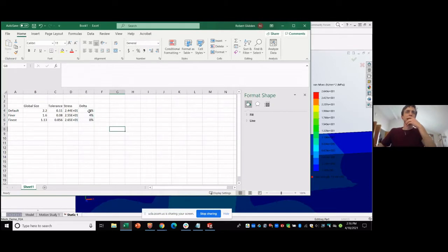To a percentage. So you can see that our stresses were 8% lower than what we predicted at the finest resolution when we used a coarse mesh. 8% doesn't necessarily sound like a lot, but when you're solving problems in aerospace in particular, and when you're doing fatigue problems, which you're not doing admittedly as students, that's a big difference, and that'll eat up all your margin.